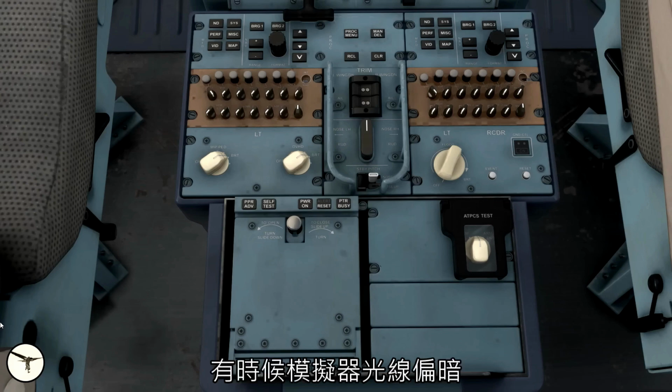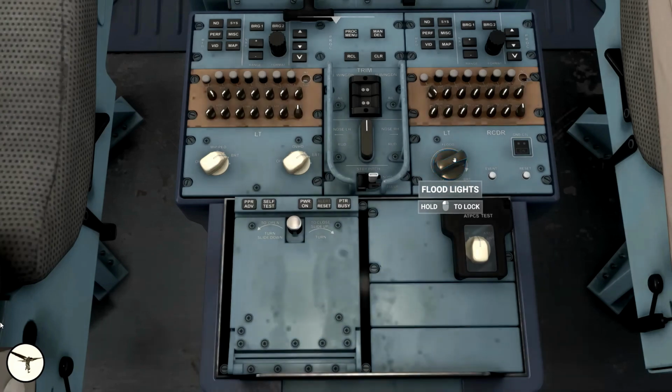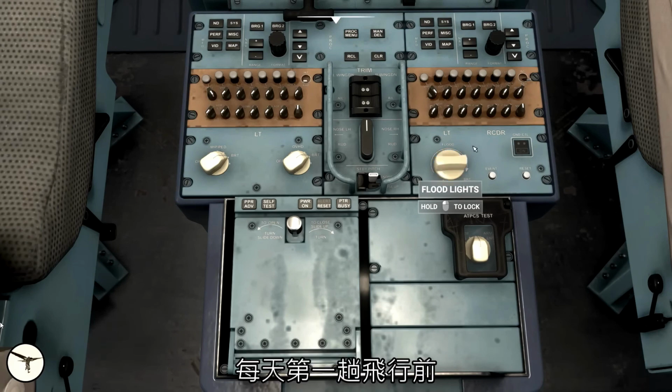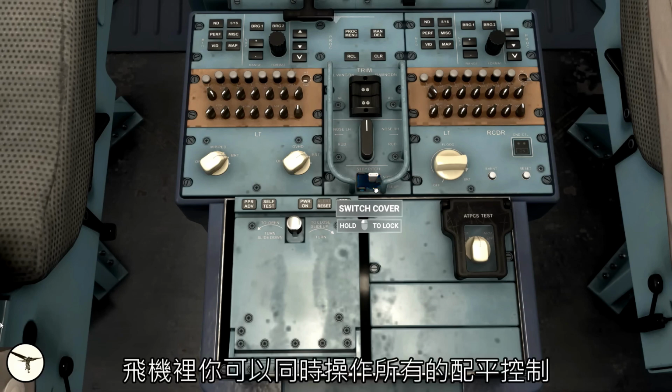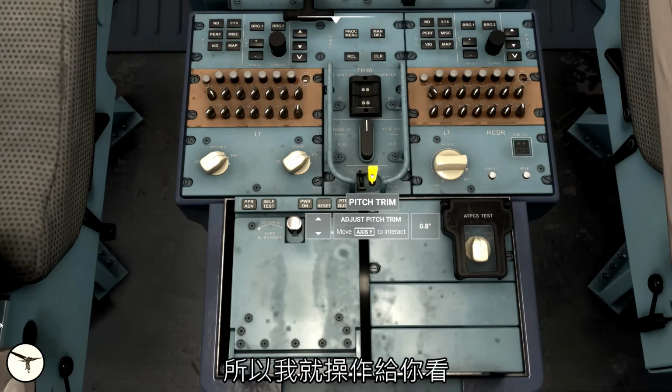Panel lights. Sometimes the panels are a bit dull in this simulator, so we can select the lights on. Before the first flight of the day, we test all trims to full deflection. And that takes some time. In the aircraft, we can apply all selectors at the same time. This is not possible in the sim, so I will just show the operation here.